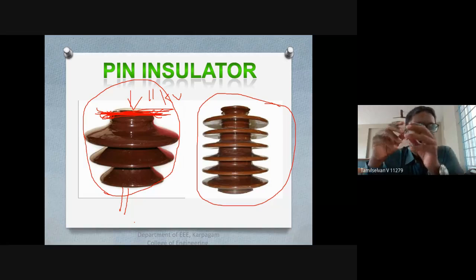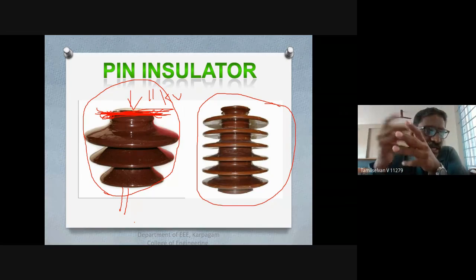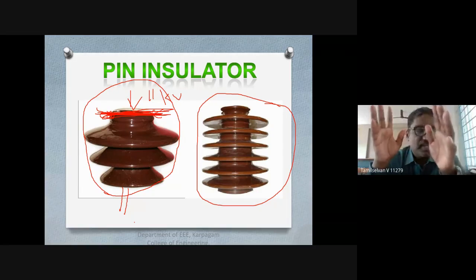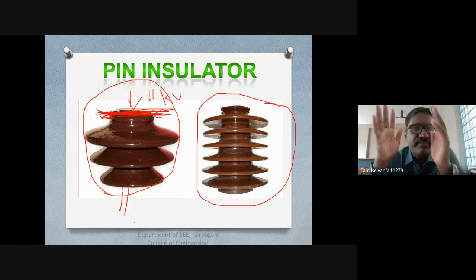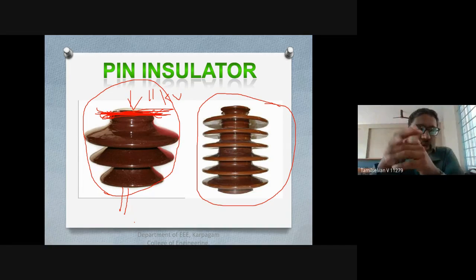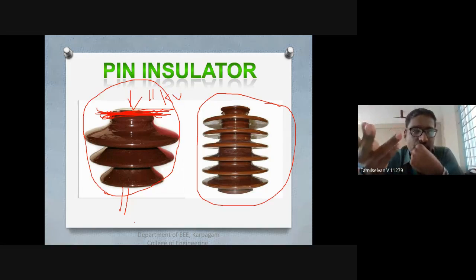So here, the cause of insulator failure is going to be often there. I have told you the property of the insulators, but insulators require high withstand. It means both the mechanical and the electrical stress. Mechanical strength is primarily to do with your line voltages and may cause the breakdown of our insulators. Electrical breakdown in the insulators normally occurs either with respect to flashover or puncture. Flashover or puncture.